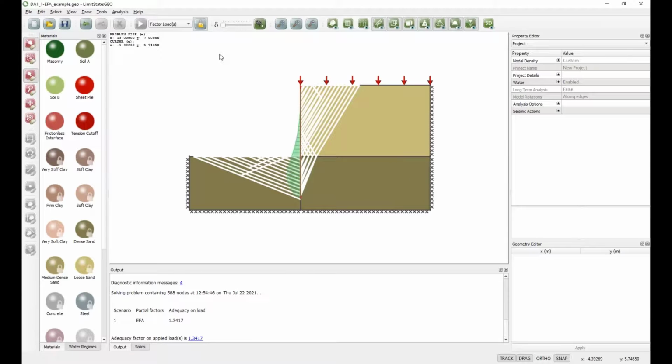Now, if we look at that analysis, we can look at the bending moments, and the software provides a plot of bending moment at the ultimate limit state, and it's coming up with a maximum number of about 125 here. So we could just take that result and multiply by 1.35, we get a value of 170. We could say, well, if we design our wall with that strength, then we should comply with the code, and we would comply with the code.